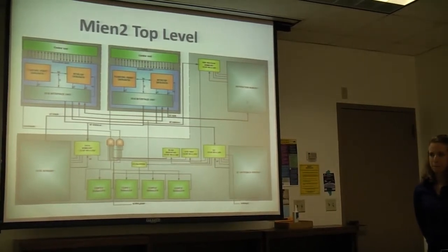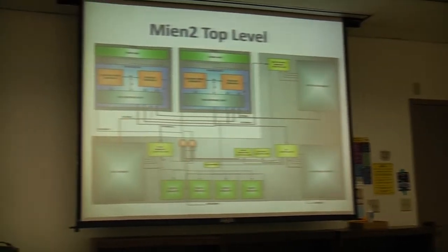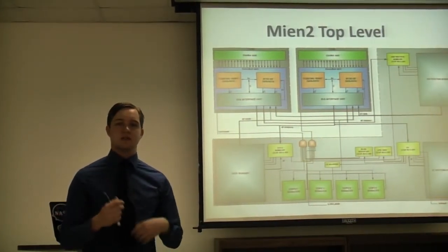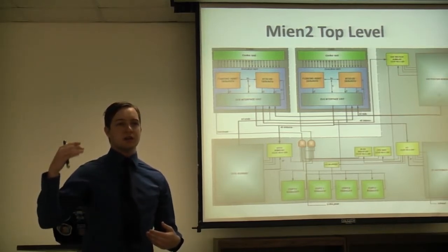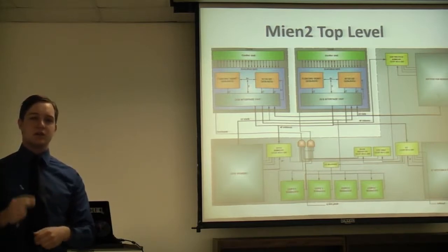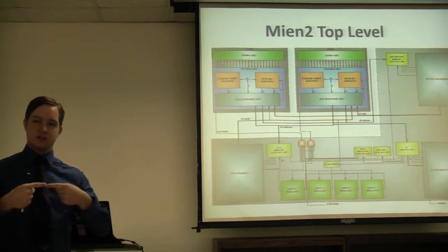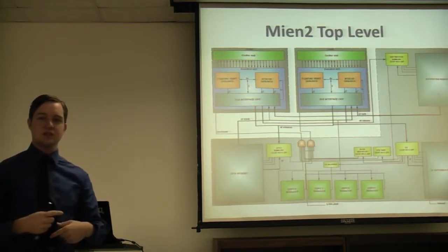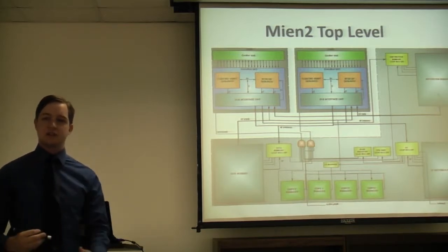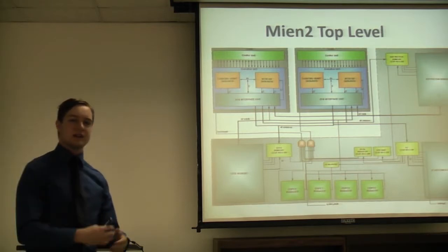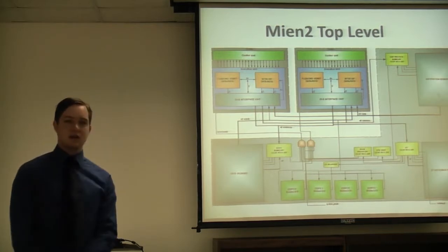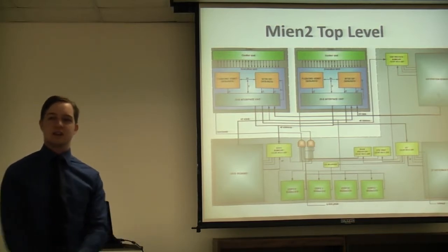The implementation, the memory module 15 as we called it, is a duplication of memory module 14 running twice, with each core writing to different memory locations. Core 0 starts core 1, tells it where to write its data to, and waits for core 1 to begin and synchronize using the core wait. Once they do that, they begin execution. Then near the end, core 0 turns off core 1, and you can actually see that it finishes its last write cycle, and it is hung and paused there until core 0 tells it to begin again, but core 0 halts, and that's the end of execution.